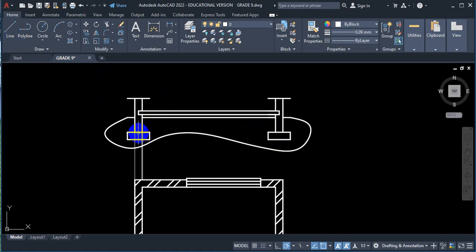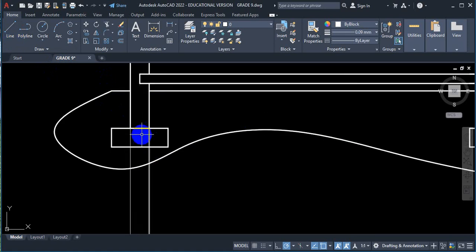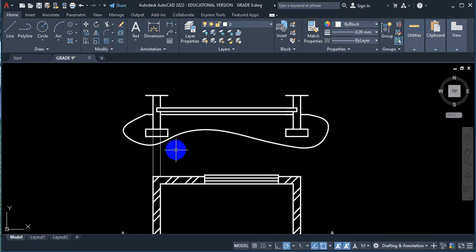Now, how then do you position the foundation? We then say, if this is 5, so this is the midpoint, then it means dividing by your scale, this is halfway, you go half on the left and then half on the right hand side. That's how you get your foundation. Then you follow all your dimensions to complete the rest. All the time, the view must line up with the floor.